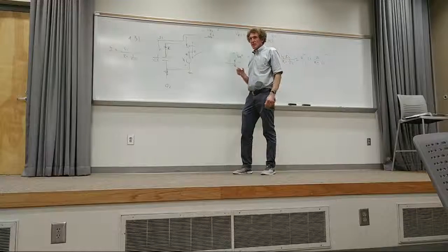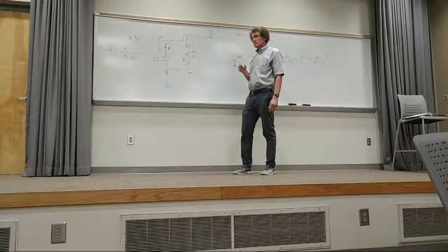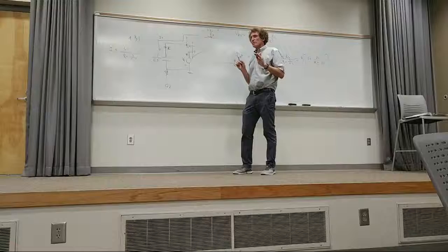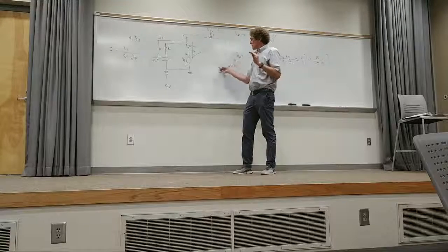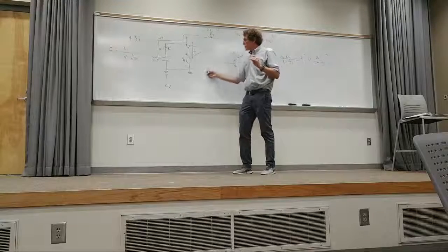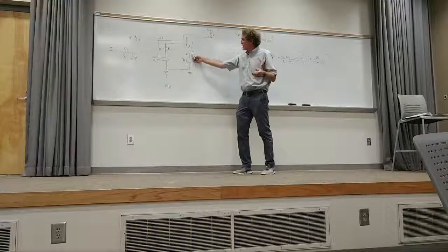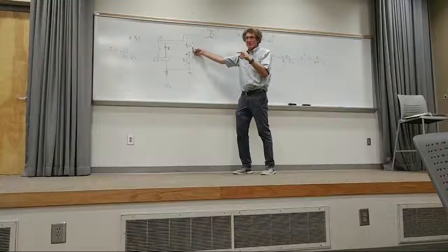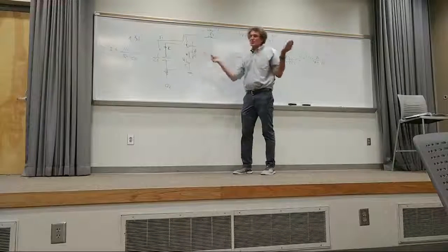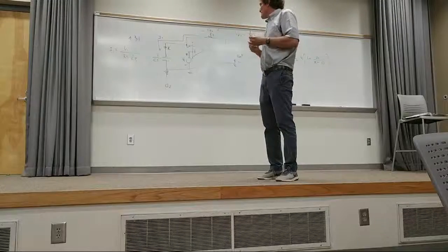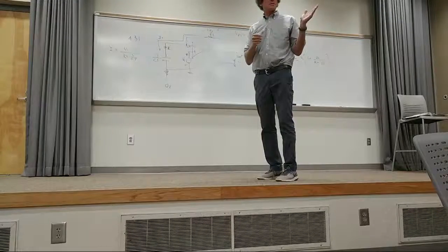Are you with me? What I was saying was just, it's going from the minus to the plus on the V1. Then it goes inside that thing from plus to minus. I'm trying to figure out what you're asking. The way I'm going around is from here to here. That's an increase. And then you don't go inside of that? Well, because this is the same voltage as here, I can just jump over to here, right? There is no voltage change between those terminals, so you don't have to take a delta either. Are you with me, class?